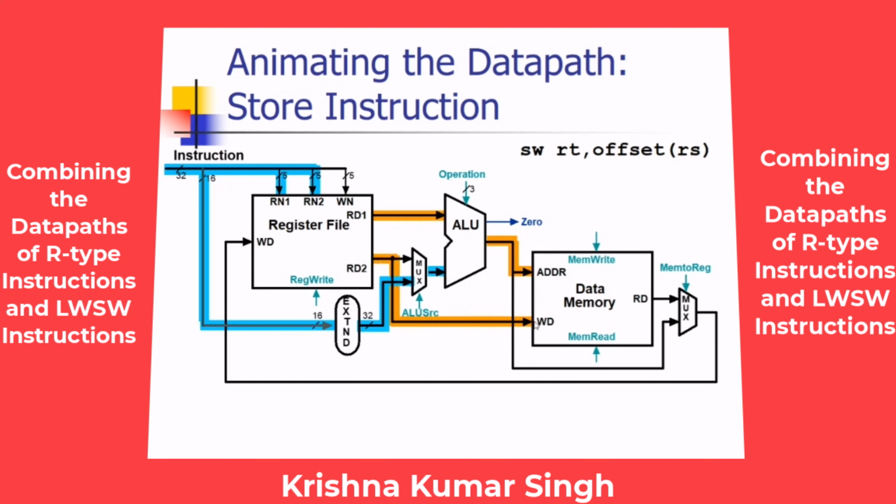And the second register is given to the write data port of the data memory. And we don't want to write back the result inside the register file. Therefore RegWrite should be 0 and MemtoReg can be 0 or 1, so we can consider it a don't care.